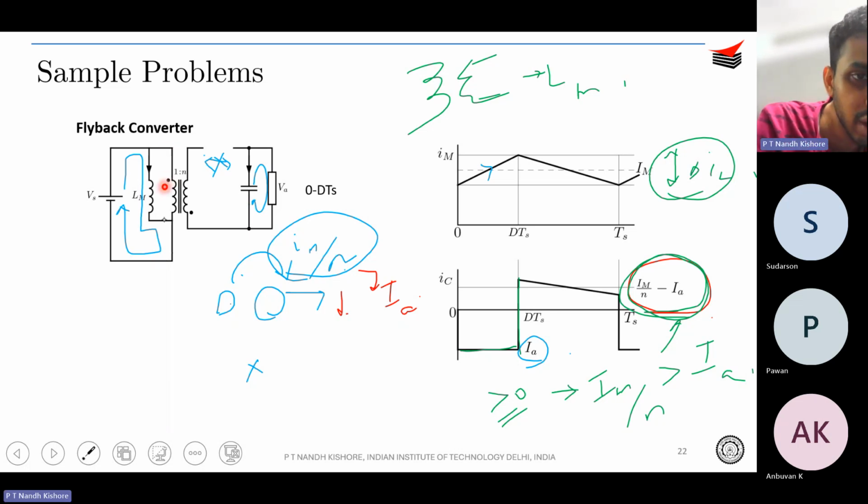Only then can it freewheel, right? The dot needs to be over here, and it should be the opposite polarity over here. That is one more thing. Conventionally in a transformer, you have both of the dots aiding. That is what we tell, right? But over here, the dots are opposing, correct? And this dot is also responsible to ensure that your current freewheels, or the current goes something like this, during the freewheeling period.